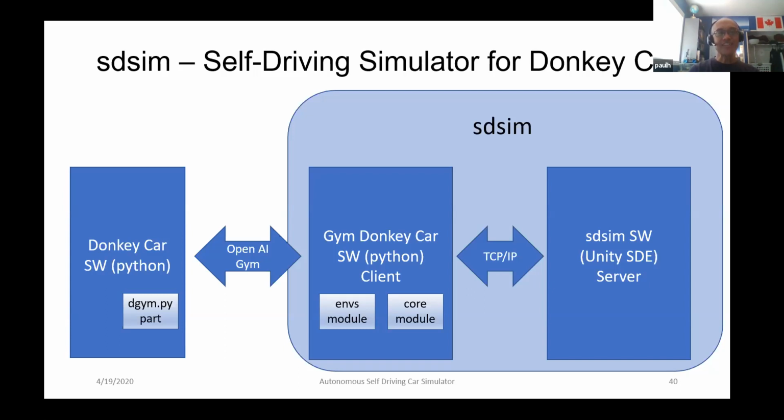The sandbox here will only be fired up if you set the path to the simulator and it's local. So you have to remember that. If everything is on your host PC, then you could say sim path equals and give it the path. Then this command can go into your path and fire up that executable because it lives on that host. But it doesn't have to be that way.